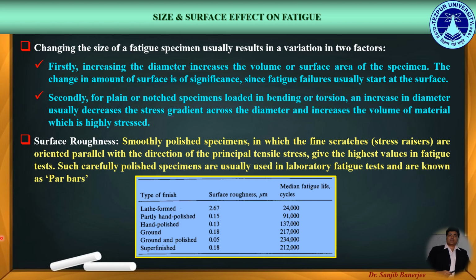Secondly, for plain or notched specimens loaded in bending or torsion, an increase in diameter usually decreases the stress gradient across the diameter and increases the volume of material which is highly stressed.